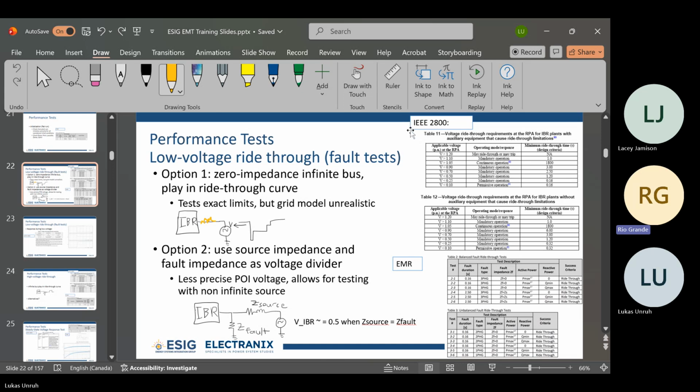The attribute is 5, and they'll say, well, the voltage is below 0.90 per unit, that's 1, 2, 3, 4, and on the 5th time, you trip offline. It's a requirement of the base standard 2000, but it's not something that's in the model space at all, even in EMT at this point. I don't think any simulation domain, unless you're the designer of the equipment doing a finite element analysis of your thermals, is going to be able to actually test it. So it's always just a counter.